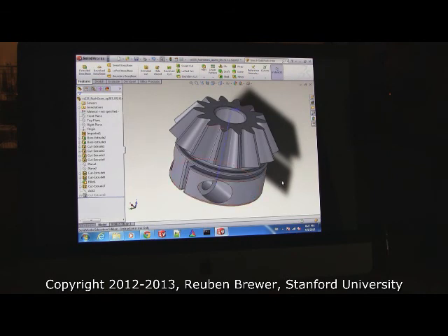Can someone remind me why we're using fillets? There are two reasons. Strength, and I may not have been loud because it was just the front row. When we 3D print them, sometimes it gets a little grumpy when we have sharp edges. They'll have little burrs on them. When we round the edges, it gets rid of those so we don't have to do much post-processing.